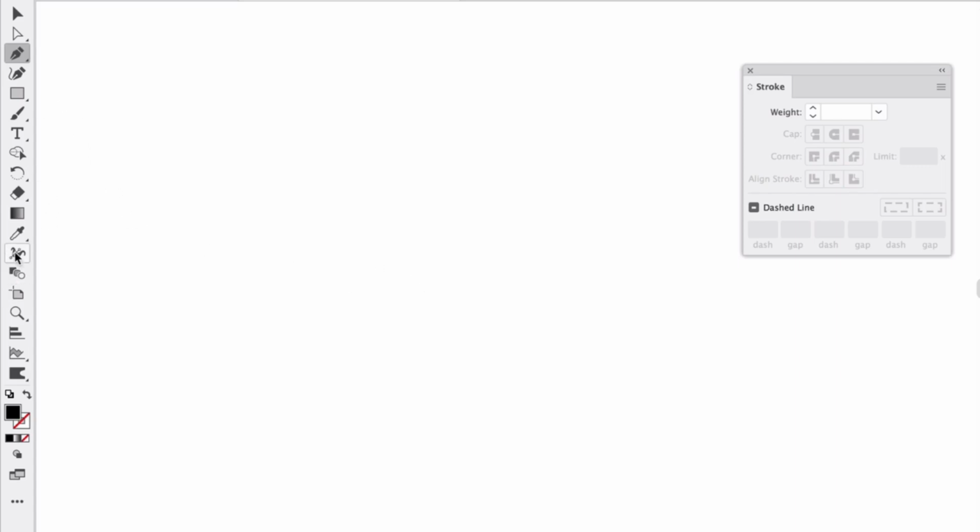So let's try to do a shortcut and use the width tool and see if we can create a very quick shield icon. Let's grab our pen tool, and we're going to just do an up and down vertical stroke. Just make sure we flip that to stroke. Grab my width tool and let's create a shield graphic. Let's make sure it's even, the top and the bottom.